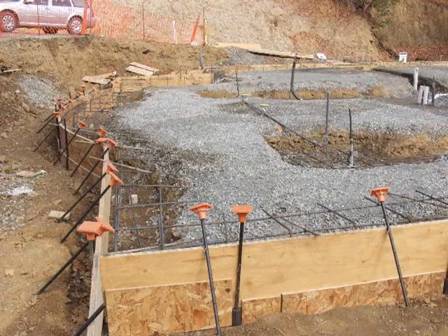Curved walls are a nice feature in any home, and they're actually quite simple to do with concrete. It may seem difficult from the outset, but it's actually quite simple. Basically what you want to do is a lot of extra staking along the curved section to hold the bend of the boards in place. Not so much for the weight of the concrete, but simply to hold the shape of the boards. So we use a lot of vertical stakes and also angled stakes along that curve to hold it in place.